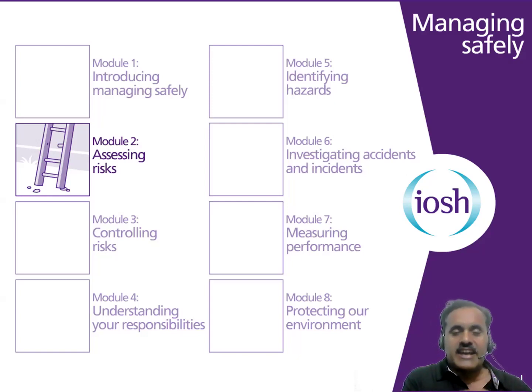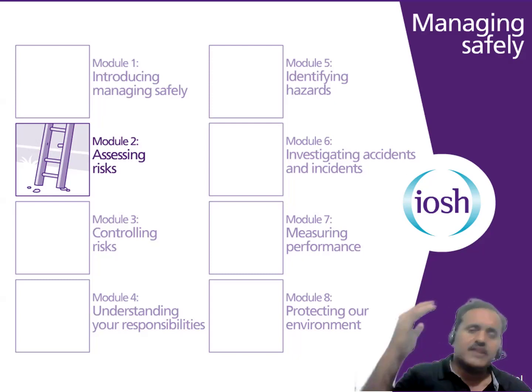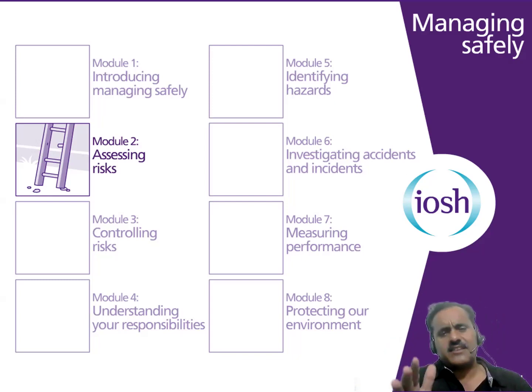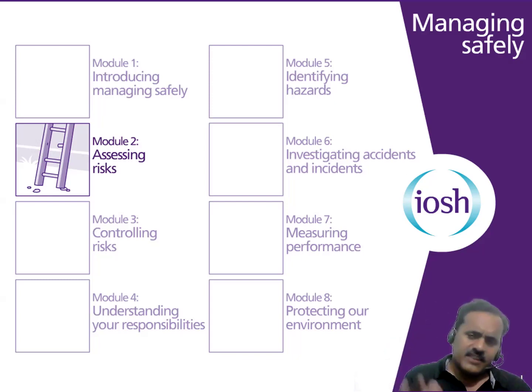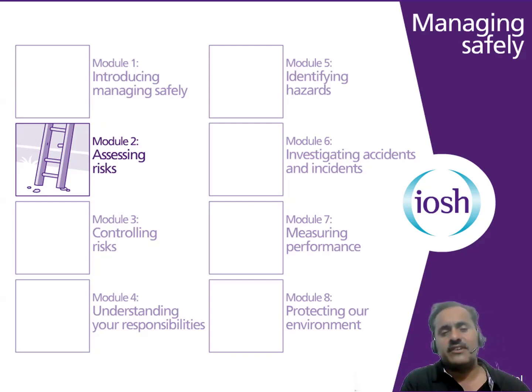As you assigned a rating scale of 5 for the naked wire which was at 4 feet height, now the consequences will remain the same, whether we talk about 15 feet or 50 feet height, because if there is contact, the result will be the same since the same voltage is there. So you would be giving the high rating to the consequences. So high rating consequences, 5. So you have assigned 2 for likelihood and 5 for consequences.